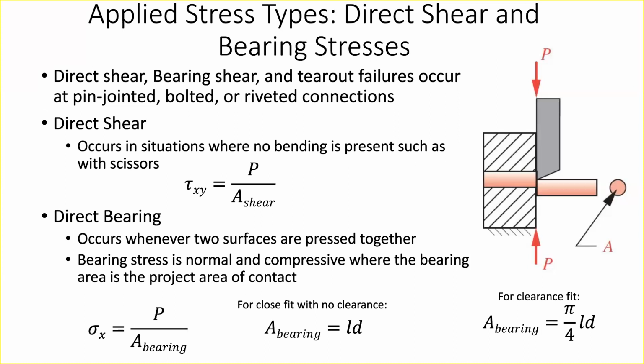There are too many examples on the vehicle of how to do this, but the most common one is that we have what are called two force members in the suspension. The constraints are specifically designed such that all of your control arms going to your wheels are only loaded in tension and compression. That's a surprising thing at first. You have this extremely high moment load on your tire as you apply normal loads to it, yet everything that supports it on the car only supports it in, I guess, purely tensile and compressive loads. And again, that's just by being extremely smart about how you constrain the part.